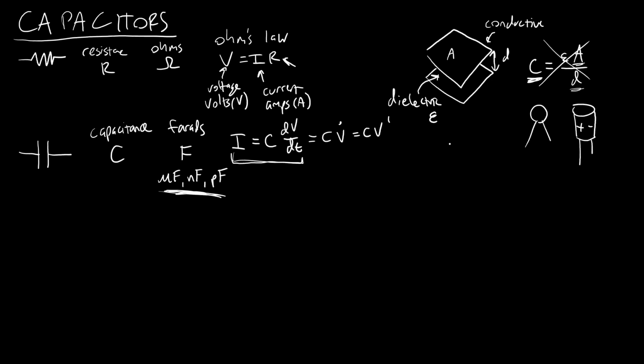You may also see in a physics class that the unit of a farad, 1 farad, is equal to 1 coulomb per volt, but that just kind of helps if you're worried about your SI units and what all these things mean. In practice, as far as we're concerned, more capacitance means it can store more electric charge. So these conductive plates with an insulator in between them allow positive charge to accumulate on one plate, while negative charge can accumulate on the other plate.